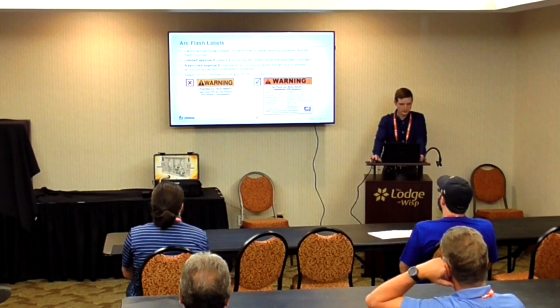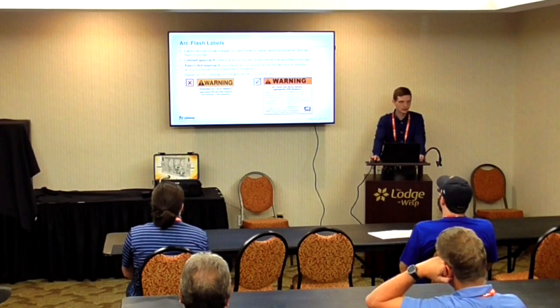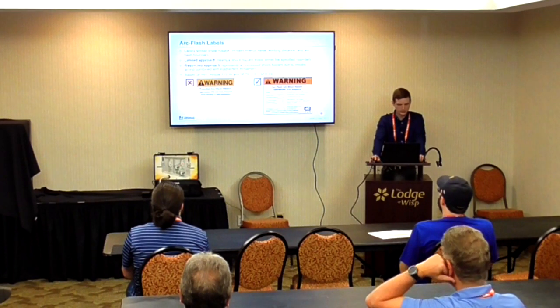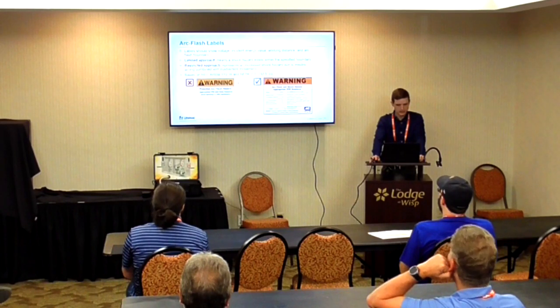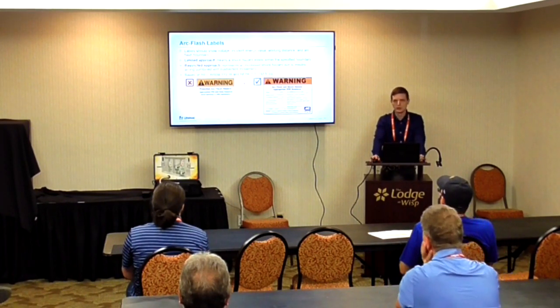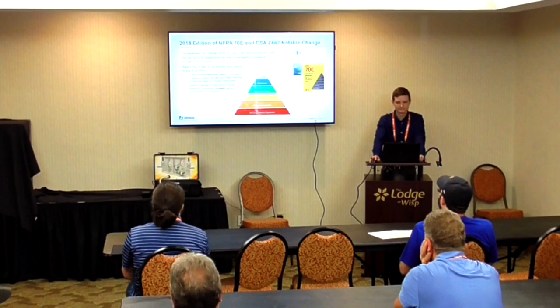This has to be visible and easy to read on your equipment. So it shouldn't be hidden on the side of it or tucked away in the back or damaged or scraped up. It does need to be readable so people can actually use that. This is an example of what not to do. This doesn't really tell you anything. It says, okay, grab some PPE, but how do you know what PPE to get? So it is important to actually do the arc flash hazard analysis and determine all of this required information.